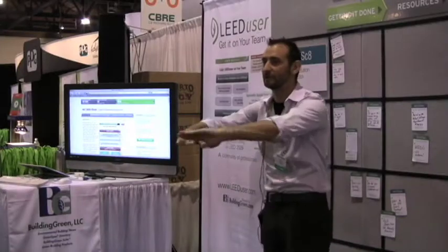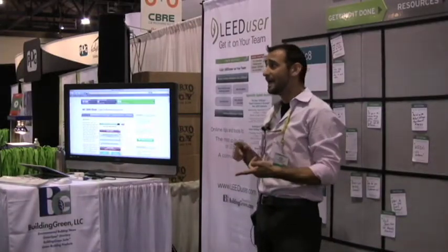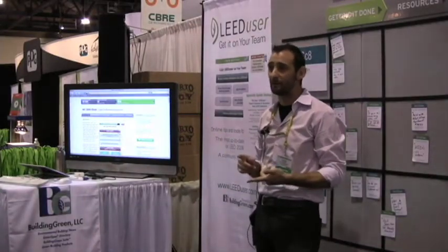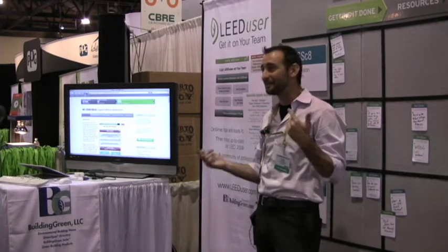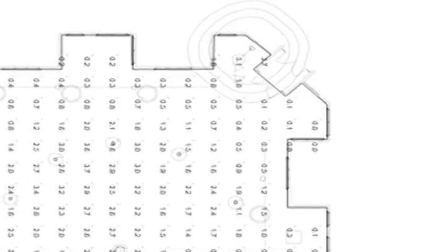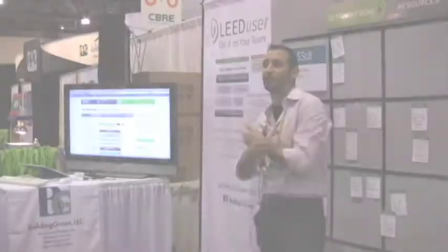Once you get to the site boundary, both horizontally and vertically, the amount coming through is near zero. The only way to do that is through a computer model, a photometric site plan. If your lighting designer is not planning to do that, then you need to make sure that it is part of the program so that they can do the documentation, otherwise they can't do it.